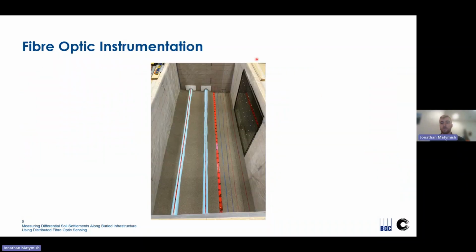Transitioning to the current experiment that we're going to focus on today, this experiment included 2 test pipes highlighted here that were instrumented with fiber optic cables and were part of a larger study to investigate the response of buried pipes with and without axial restraint. And then on the right, we included these 5 fiber optic cables, which we selected to represent a range of cables that may already be buried beside a pipeline or may be installed to monitor or detect ground deformation.